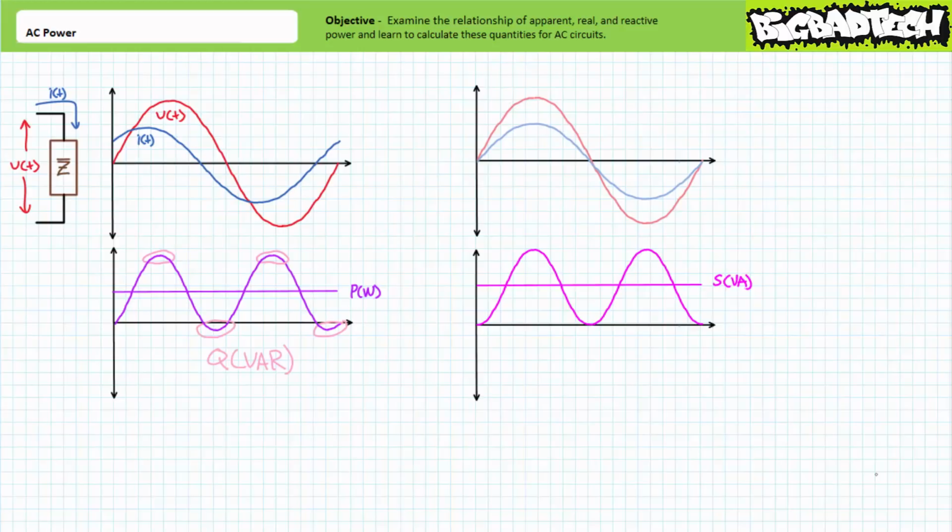Reactive power Q is somewhat difficult to visualize graphically. However, here's how I like to think about it. Whereas real and apparent power can be thought of as simple straight line averages running right down the middle of their respective plots, I like to think of reactive power as those periods of negative power and their matching positive periods cyclically exchanged between the circuit and source.